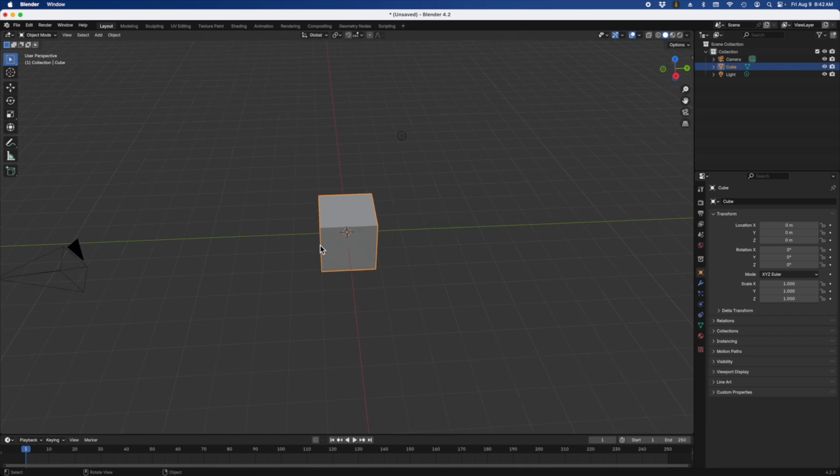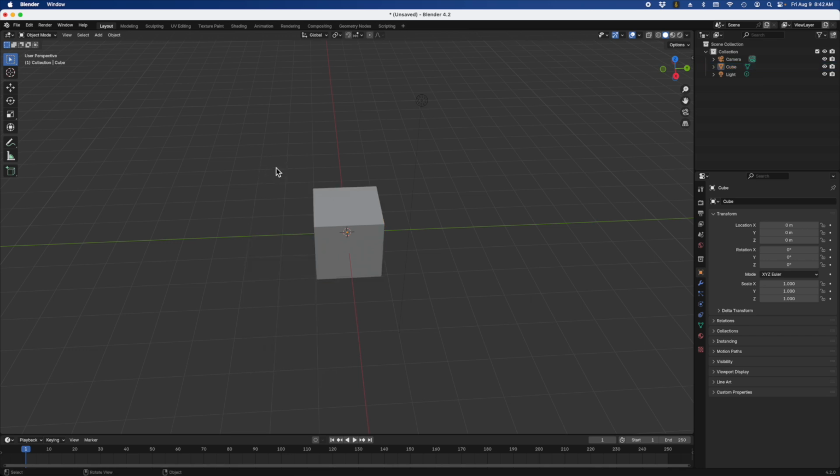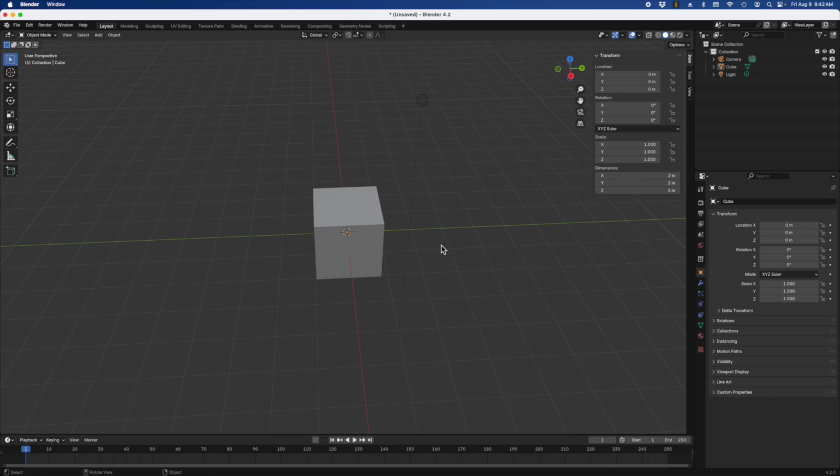One of the other things that you'll need to do is get familiar with the N tab panel. It's called that because you press the N key to bring up the N tabs panel. I'm going to go ahead and do that now. Press N, and I've got my cursor in the 3D viewport. You'll see that these little tabs show up when you press the N key. If you want to hide that, press the N key again, and it goes away.